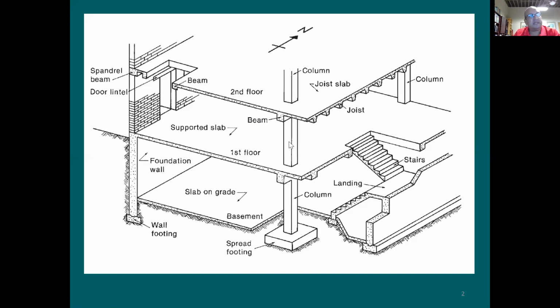If I cut this column section right here, does this support the second floor or the second floor and first floor? Right here. Can I say this section here? It's what? Just the second floor. Just the second floor. Very good. So I'm going to be taking it down here.